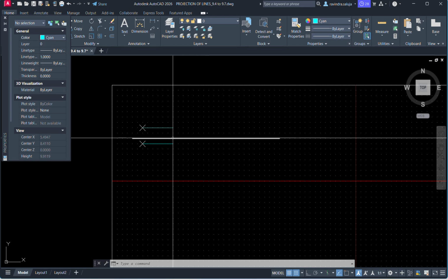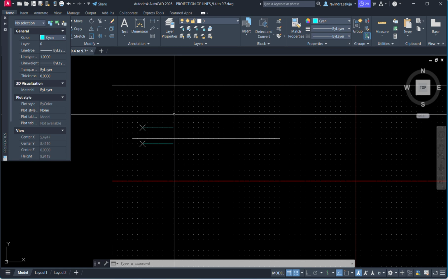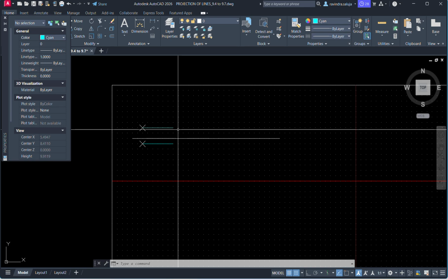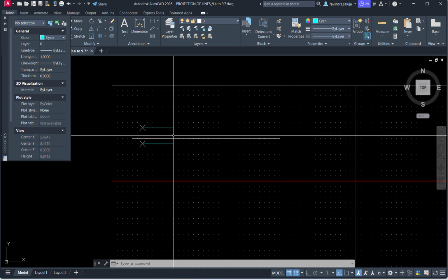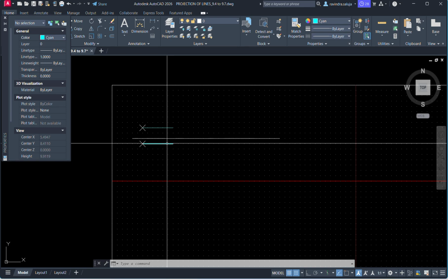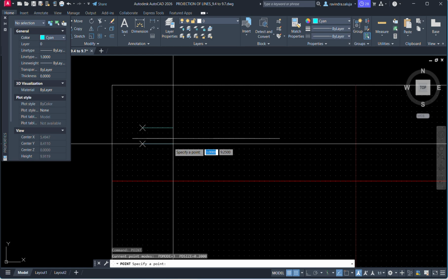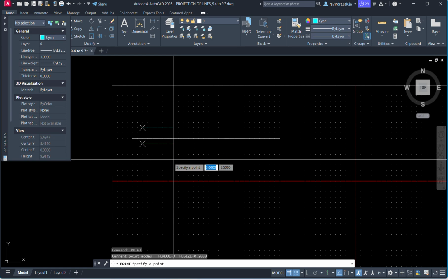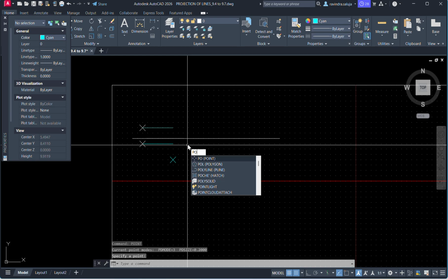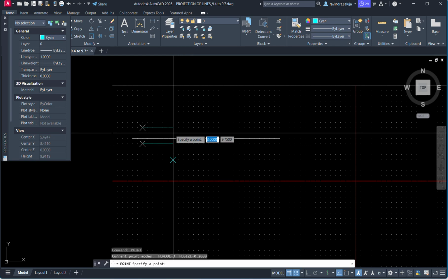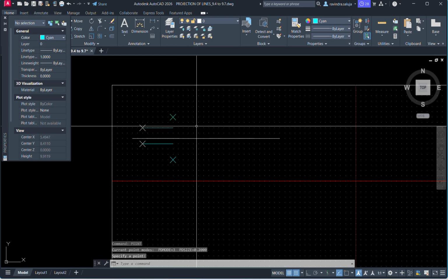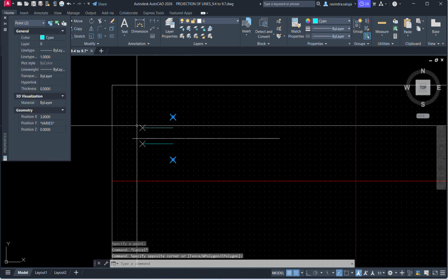Fine. Now we are going to take the point B position. Point B is 100 mm behind the VP and 100 mm below the HP. Below the HP means below your reference line. So 100 mm from the reference line, we are going to mark point B. So 1, 2, 3, 4 grid spaces. Similarly, the point 1, 2, 3, and 4. If you want, you can change the color of these 2 points.